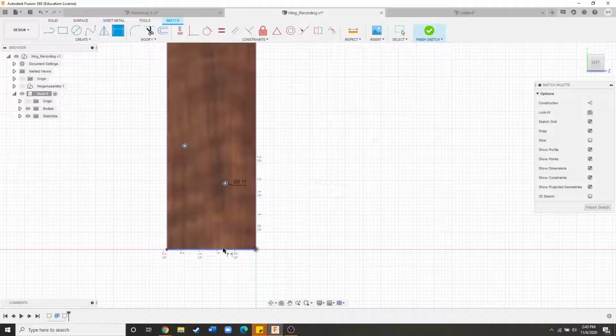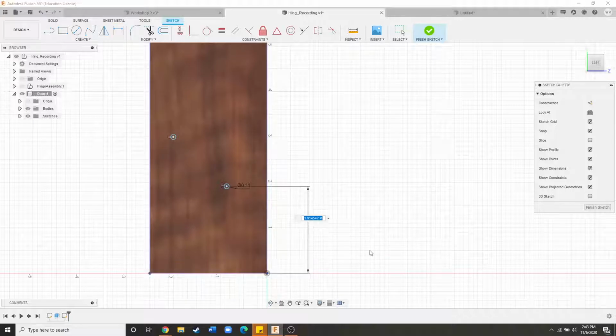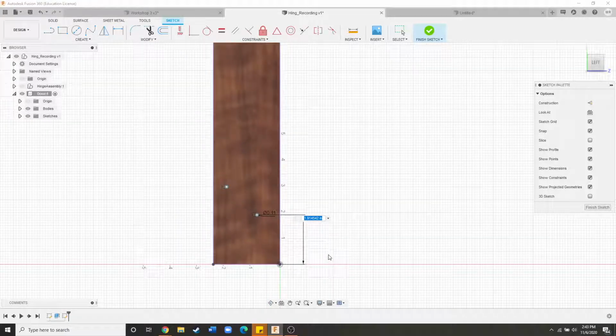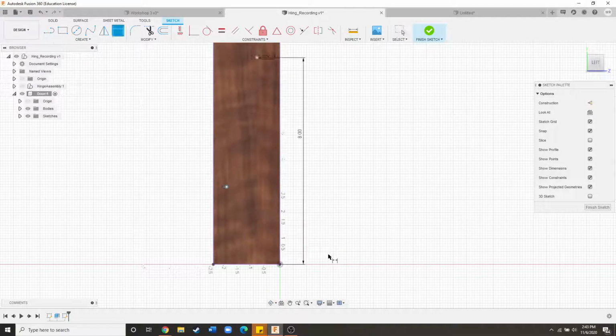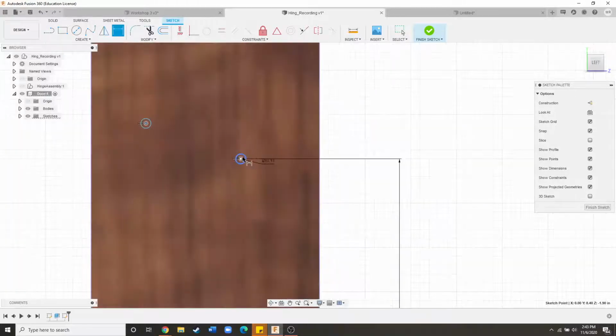So now let's just define these holes relative to the bottom of the door. Again, if we had a door that we were designing for, we could actually make this more realistic. But let's say it's 8 inches from the bottom of this door. And then let's go ahead and pull this hole up a little bit, and it's going to be 1/2 inch away from the other hole vertically, because that's how we made the hinge. And this other hole here, or this hole on the left, is going to need some horizontal definition from the hole on the right. And let's say 1.5.